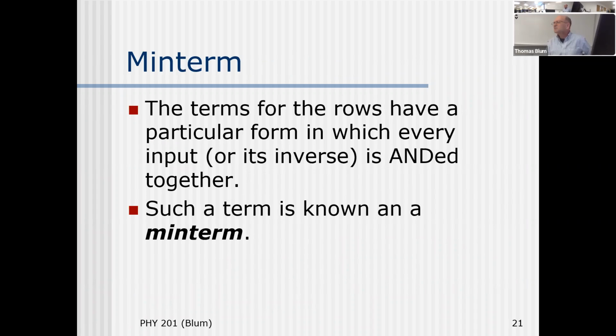We will learn next week how to simplify. If you simplify a sum of products, you will probably still have a sum of products. But you will no longer have a minterm. Minterm means I did the basic thing, all the terms are there. Every row has all the input terms there. But if I don't ask you to simplify, you don't have to simplify. Okay. So people spend their time simplifying when I never ask them to.